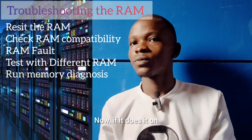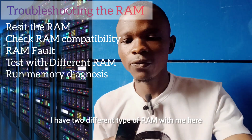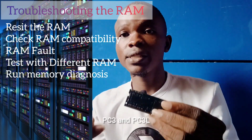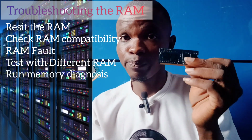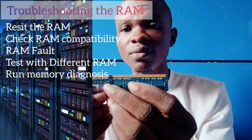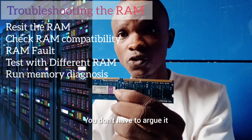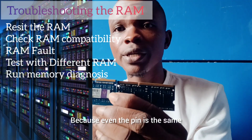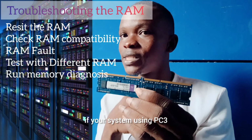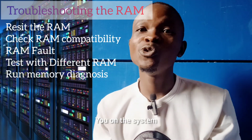Now, if it doesn't come on, you will check the RAM compatibility. I have two different types of RAM with me here. I have PC3 and PC3L. Now, this PC3 and PC3L actually look the same. You don't have to argue it. They are even the same because even the pins are the same. So if your system is using PC3 and you added PC3L, it will not come on. It will not display. You turn on the system, it will not come on.